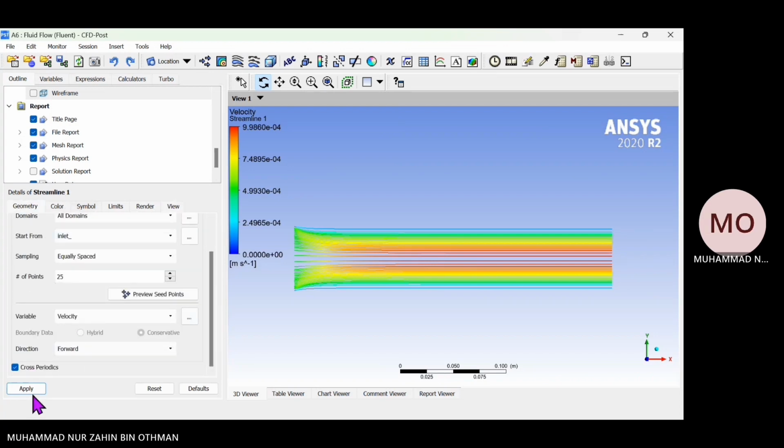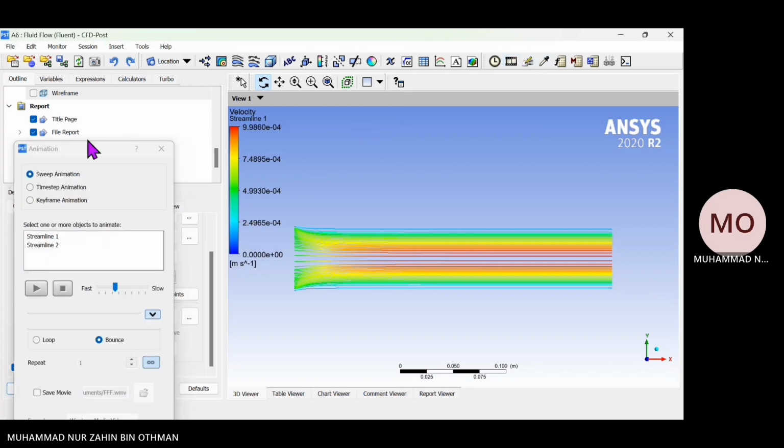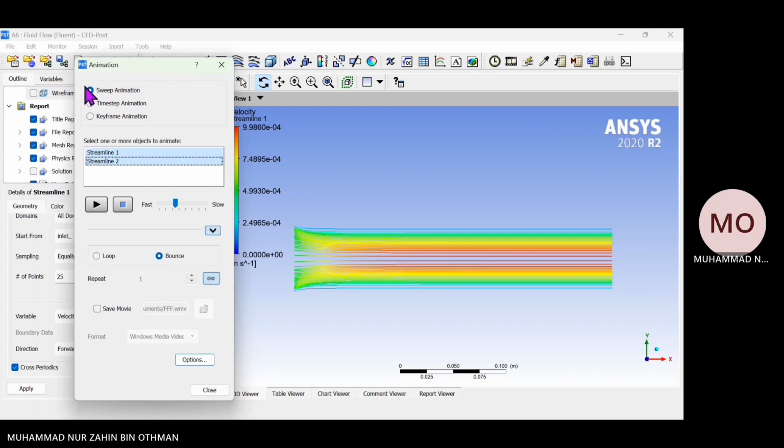Animate the flow in this pipe domain using quick animation option. You could also modify symbol size and spacing. Save the animation by choosing the file save location.